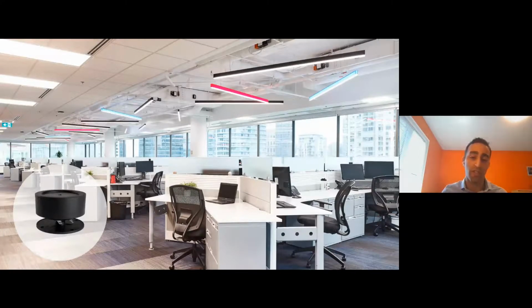This device serves the same purpose as a loudspeaker, but can be used in applications where loudspeakers cannot. For example, you can install a transducer on rigid surfaces like a gypsum ceiling in order to preserve the ceiling's clean appearance. It can also be installed on doors, windows, etc. to help thwart some methods of electronic surveillance, such as which may happen when someone's trying to eavesdrop. It emits sound by vibrating the surface it is attached to. It converts the surface to a speaker. It's important to note that the vibrations of the surface emit airborne sound, and the resulting acoustic energy is not experienced in the form of physical vibration.